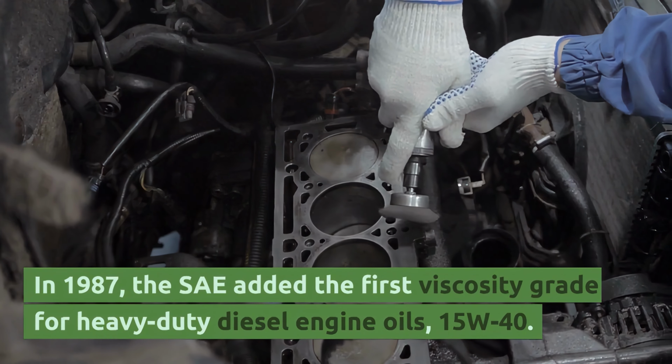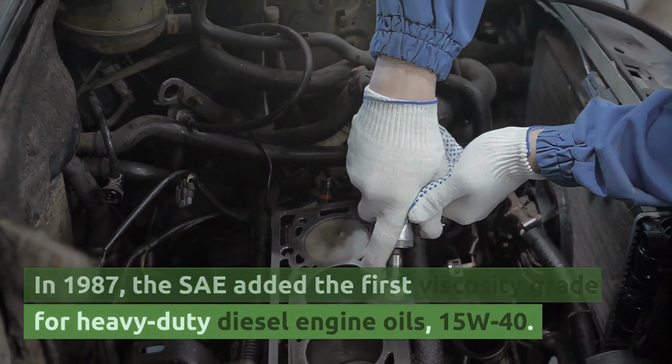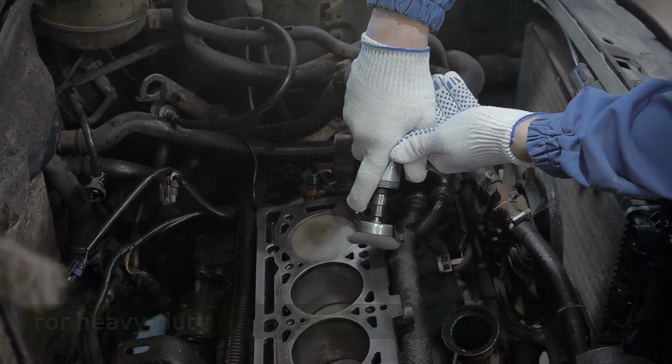In 1987, the SAE added the first viscosity grade for heavy-duty diesel engine oils, 15W40. This was followed by the addition of several other viscosity grades for diesel engine oils over the next few years. In 1993, the SAE introduced a new viscosity grade, 0W30, which offered improved fuel economy and cold weather performance compared to other grades. This was followed by the introduction of 0W20 and 5W40 grades in the early 2000s.